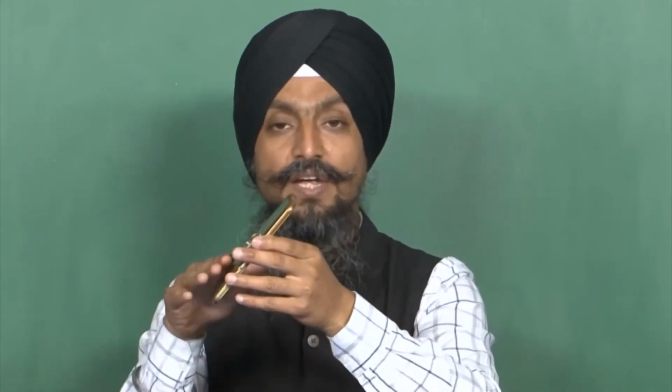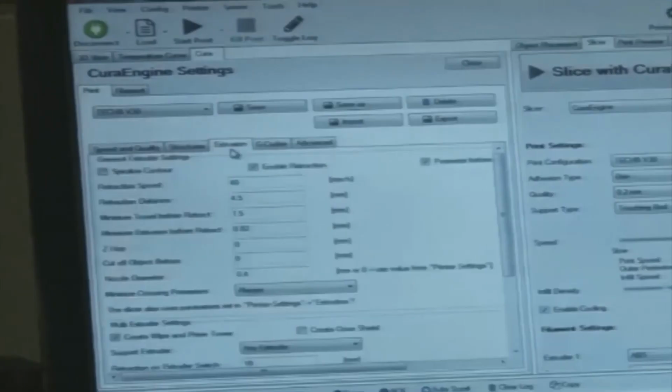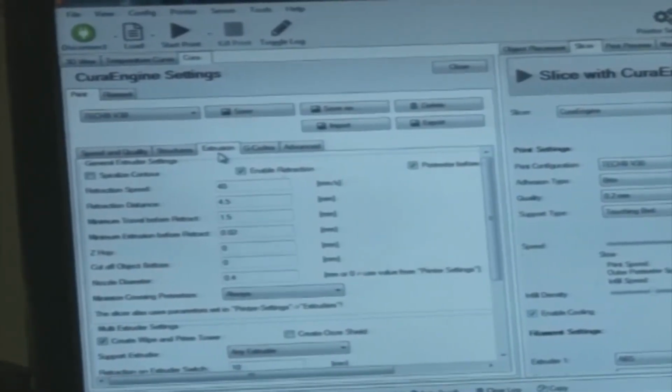So this overhang angle has to be decided, and that is fixed at 60° here. So this overhang angle is 60°, and next what we have here, we need to see whether there is anything overhanging in the CAD model. In the CAD model, if anything overhanging is there, then we need to put this angle. If anything is overhung, then we need to provide this support, and only then we can proceed further. So then the overhang angle has to be decided.